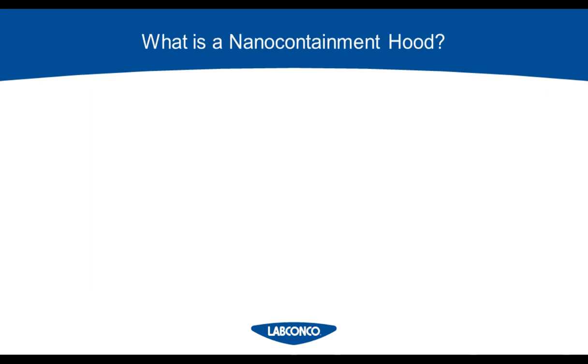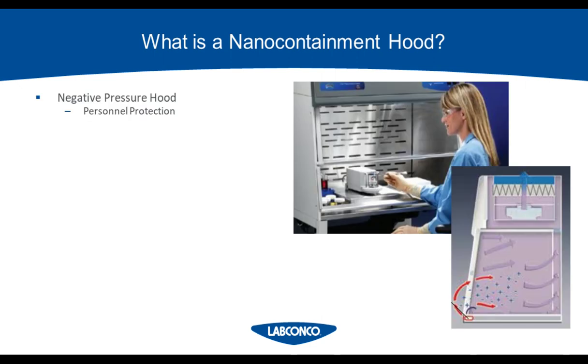So let's dive a little bit into the nano containment hood. So first off, you've got a negative pressure environment. That's a controlled airflow area that we know can help contain and trap those hazardous particles that you may be generating during a procedure. So in this cross section, you'll see airflow flowing to the back of the hood, and it's actually driven by a blower. That's that kind of whitish feature in the upper part of the hood, and then onward into a filter.